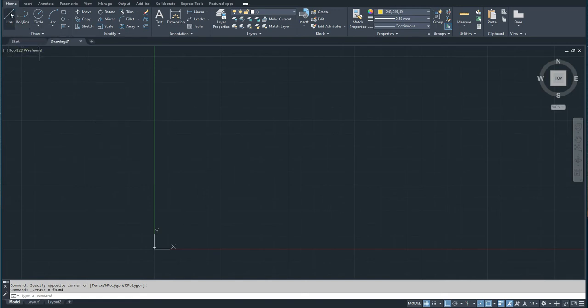Now we learn together how we can draw lines using the ortho option. But what if I want to choose the start point and the next point using the coordinates x and y? Example, I want to start my first point here. This distance, as an example, say it is 5 by 5. I will pick the line. Don't touch the mouse. Write 5, 5, not dot. 5, 5.